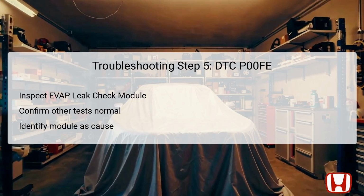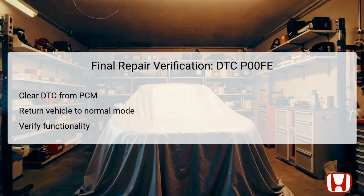eliminate the DTC. After completing repairs related to DTC P00FE, it is essential to conduct a final repair verification check. Begin the process by clearing the DTC from the Powertrain Control Module, PCM, using the HDS diagnostic tool. Once you have successfully cleared the code, return the vehicle to its normal operational mode. It's crucial to conduct a thorough functionality test to confirm that the repairs have resolved the issue and that the P00FE DTC does not reappear.